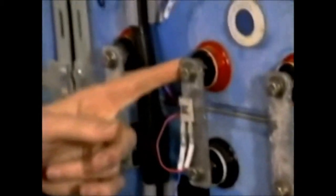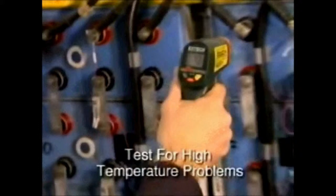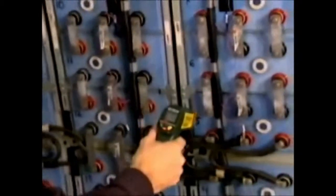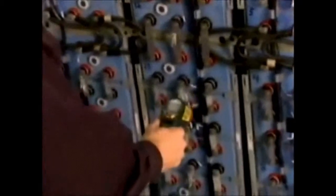As part of your setup, be sure to test for temperature, which will affect conductance measurements. Scan the entire battery system, starting with jar 1 and working to the end, concentrating on the posts and connections. When you finish temperature testing, check the reading on your sensor. You will need to enter the average manually during the setup.